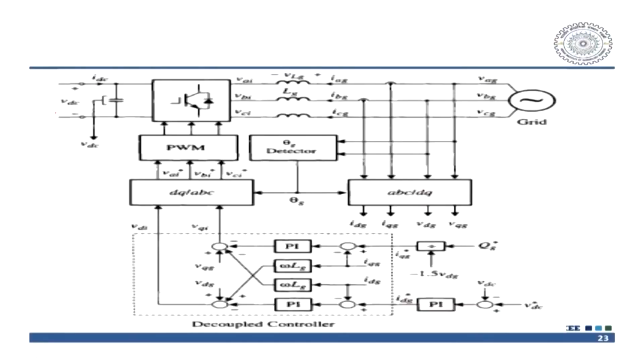So, ultimately if you have a real source, then IDC will be sinking. Assume that you have a real source and you can feed the power to the grid, and you are maintaining the value of the VDC here, and this is the converter. Ultimately you get VA, VB, VC, and thereafter you have an inductor, because it is PWM pulses here and a sinusoidal waveform there.